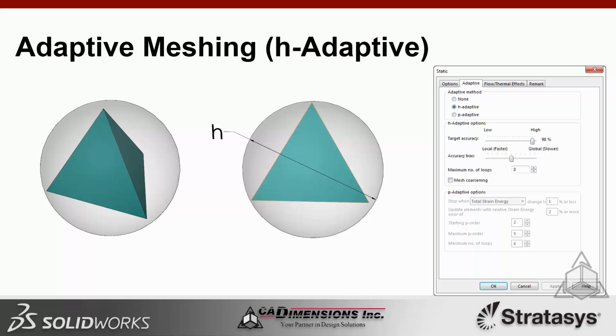So great, with this setting, I can just use adaptive mesh and not have to worry about mesh controls, right? No, not at all. Your starting mesh is extremely important even in an adaptive study. You, as the user and the person running the simulation, know better than a computer where you want to focus the mesh. You should still add mesh controls as a starting point for the solver. Let's take a look at an example of this.